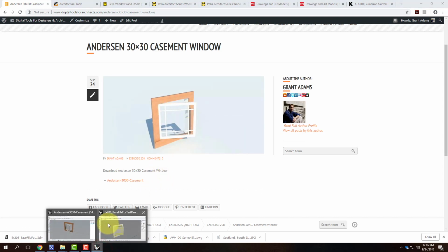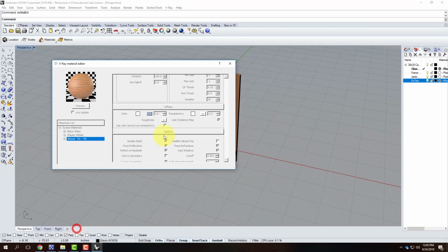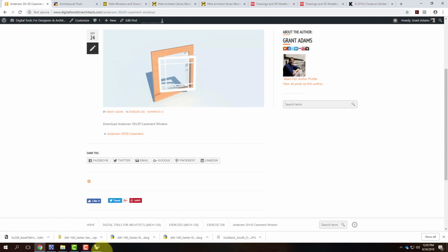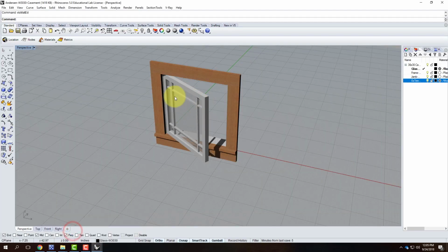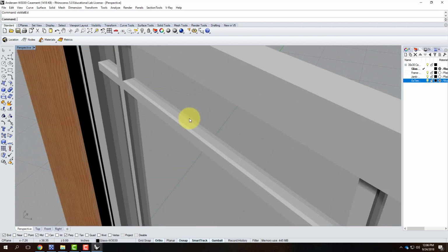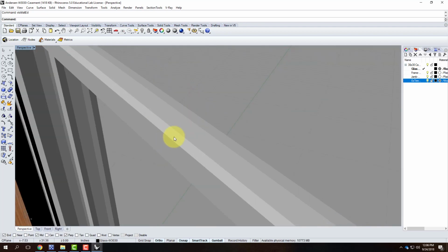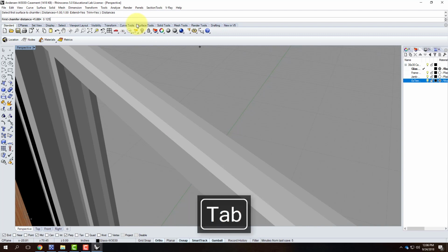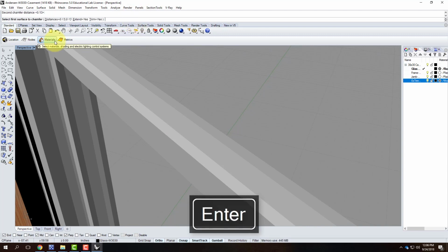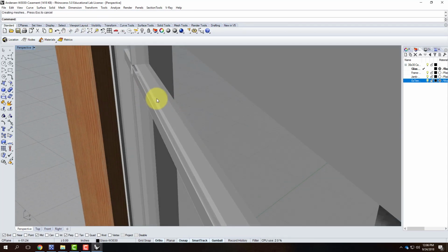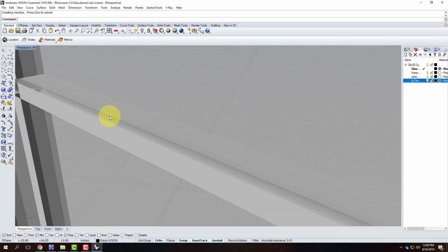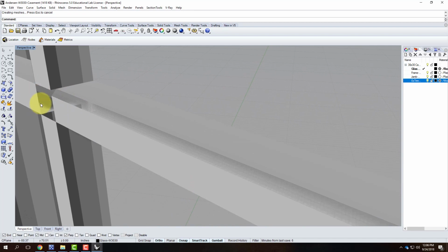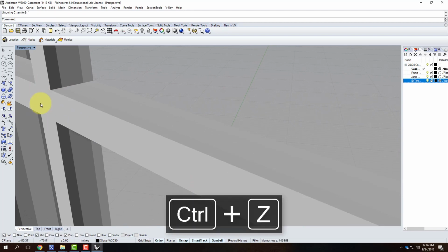The one other thing that I should mention is some of the windows, sometimes people like to do a little bit of extra fluting on a window. We did these kinds of chamfers and stuff before. So if, for example, I wanted to chamfer the corner here, chamfer SRF, distances, let's do 1/8 of an inch. There to there. And we could build those little bevels on the sides. I think I made it too big, and I should have done it before I did the Boolean join. But you can do those kinds of things.